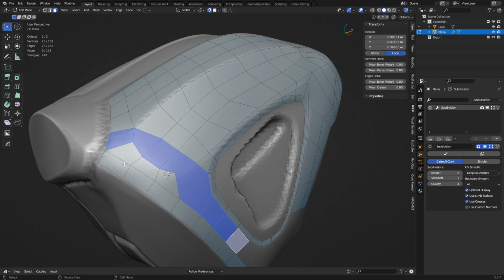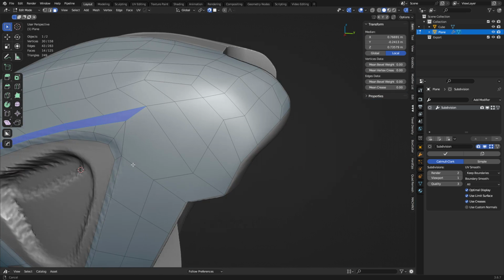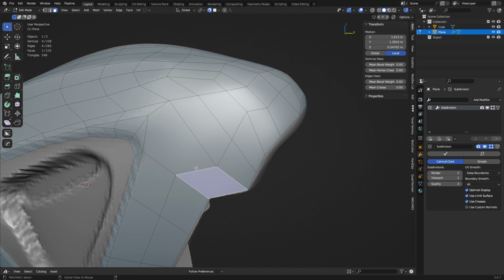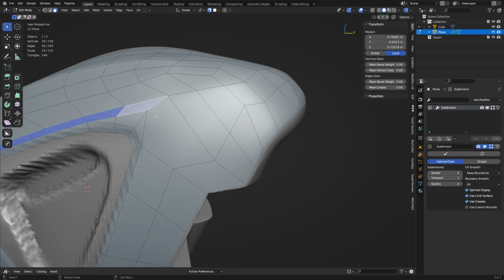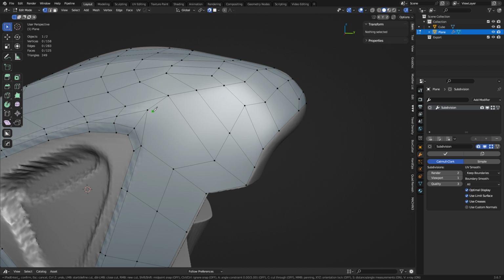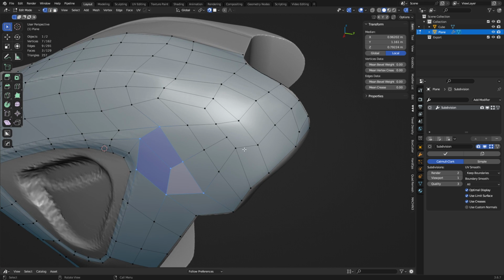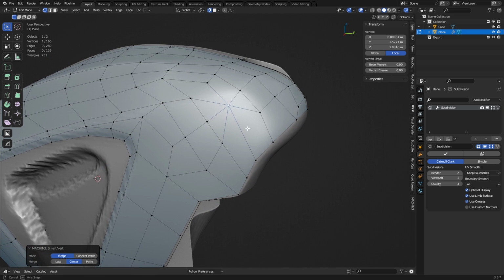Alt-click these edges and just see they're going in the right directions, basically. For the most part, those could be better, perhaps, but this one here would go all the way through there, possibly. I don't like that. So we could do a redirect, maybe. So you can also redirect or do an end pull through this kind of mesh here. That would turn it into quads as well. So it's not just cutting it in half. And that could work out, but we could do a reduction maybe somewhere like right here. Okay, we might get away with that.